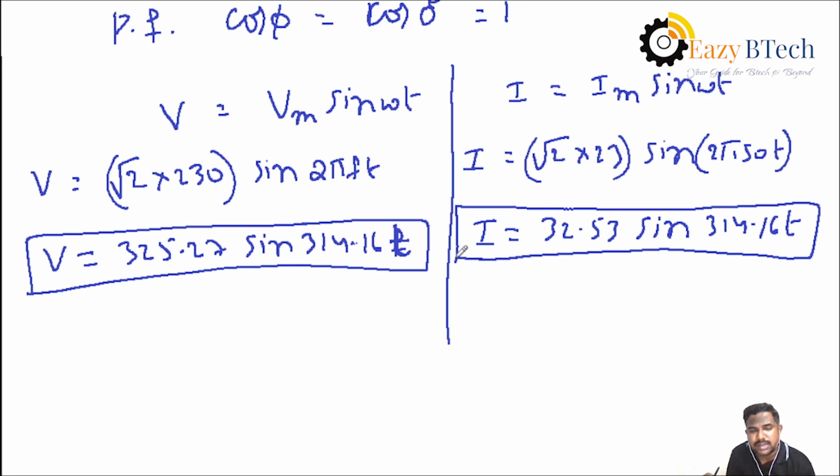In a given circuit that consists of only R, or only L, or only C, that is, only one element, you can find the total impedance value and current value. The values we find are RMS values, that is V and I. From that, we find the maximum values Vm and Im.